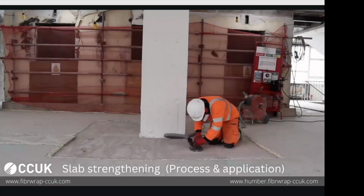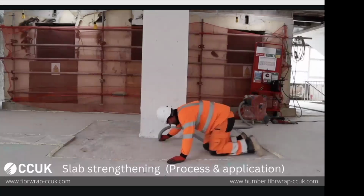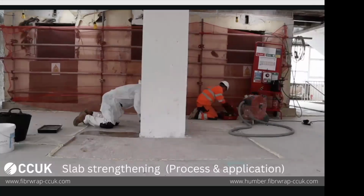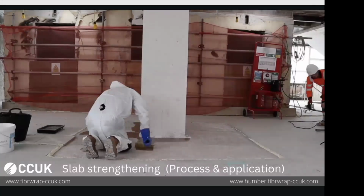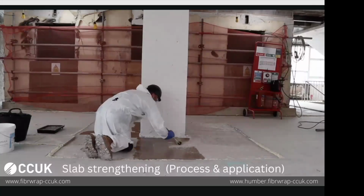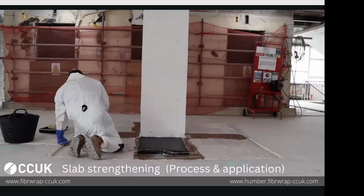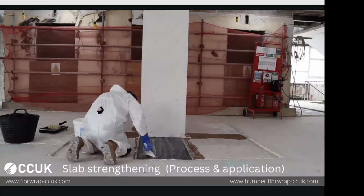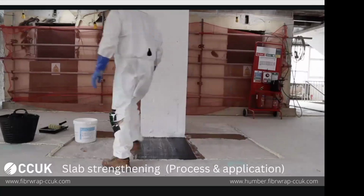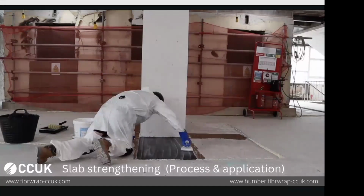Here is a brief video which shows you the application part. So the first thing you do is surface preparation, which is done by grinding the area. Then you clean the area, it needs to be dust free, followed by priming. Priming is always done using pure epoxy so it can soak into the concrete. Then they apply the first coat of thickened epoxy, which is the white color epoxy you're seeing, and they unroll the first layer of carbon fiber.